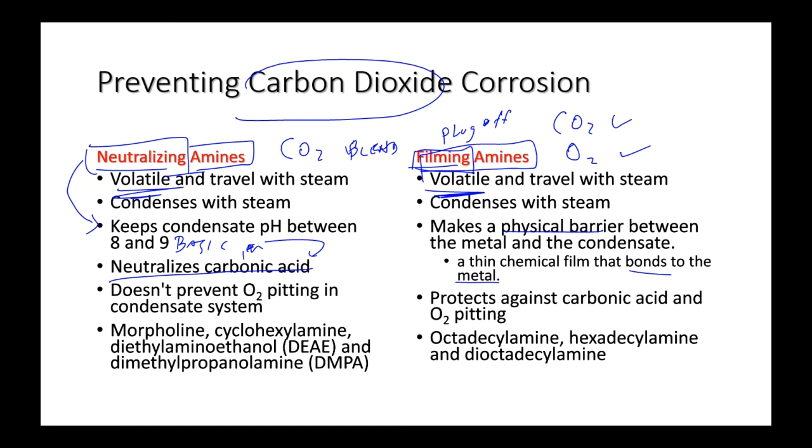It was our plant master pressure control, and the little sensing line got plugged with amine. And I noticed that the boilers stopped responding correctly because it could not properly detect the boiler pressure, the main header pressure. And I came close to tripping off the boilers.